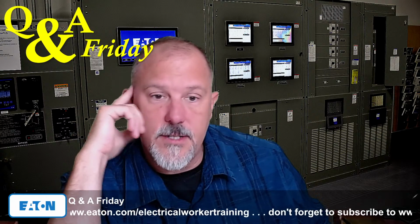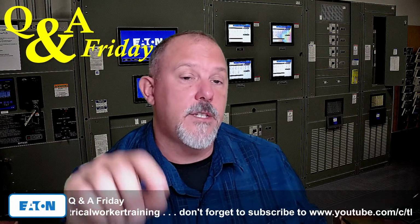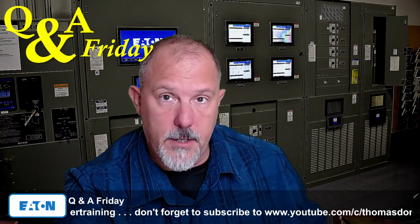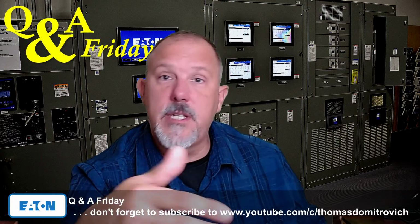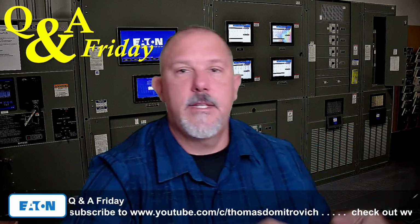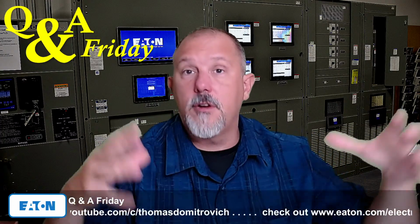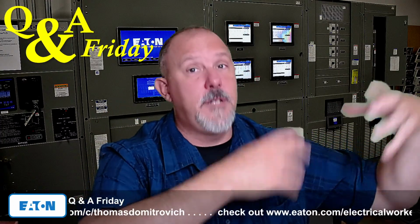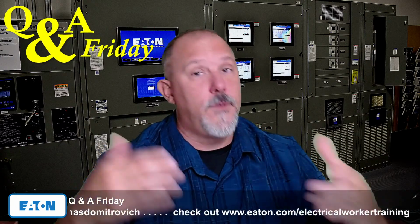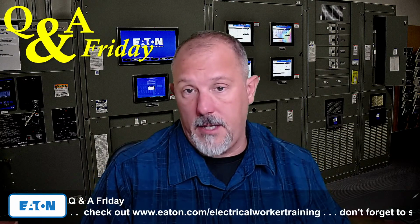There will be different circuit breaker manufacturers. Be mindful that I can't engineer series ratings when I'm dealing with molded case circuit breakers between, say, two manufacturers. I can't take my circuit breaker and say it's going to protect another circuit breaker. If you do a series rating pair, they're going to be tested together, and I'm testing with my breakers, not my competitors' breakers, because I have no control over any of the changes that they make.